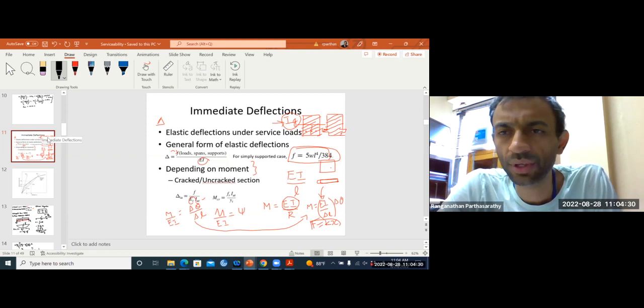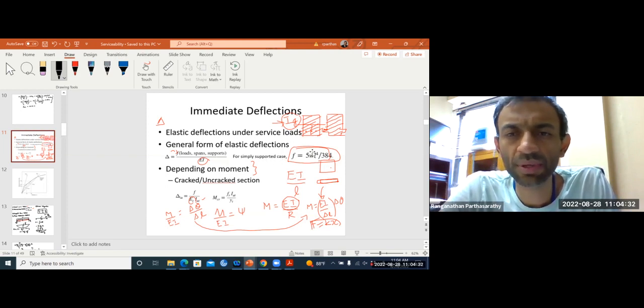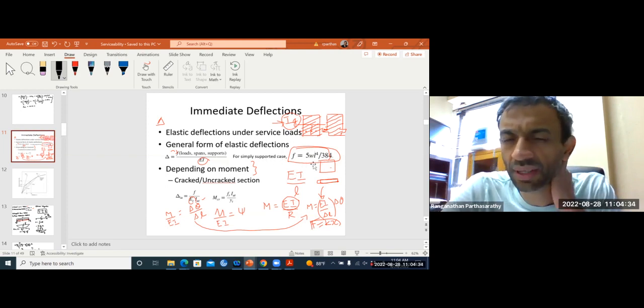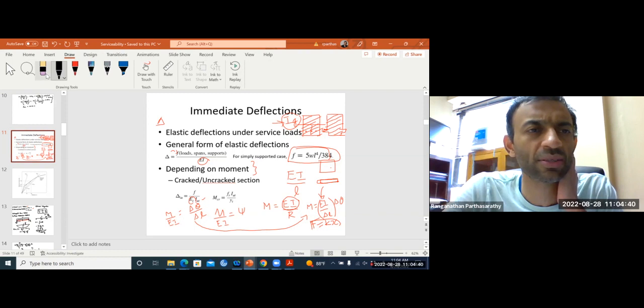So if you remember, for simply supported case, what was your deflection? 5 times wL to the power 4 by 384 EI. Do you remember this?